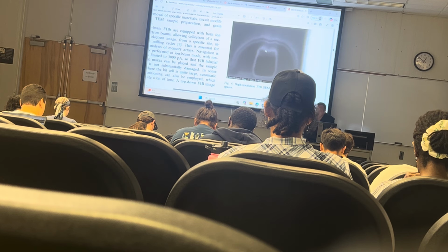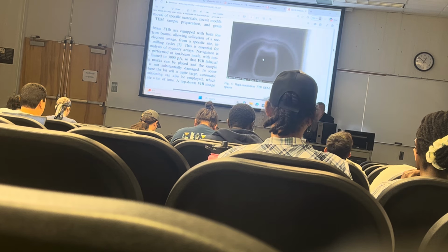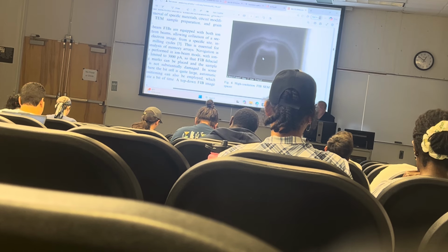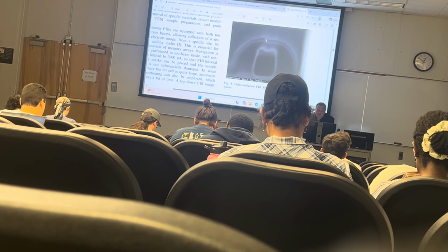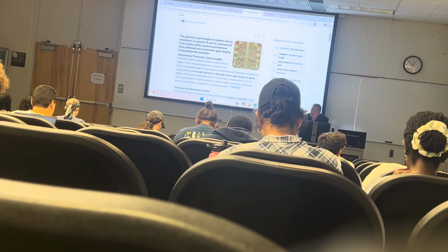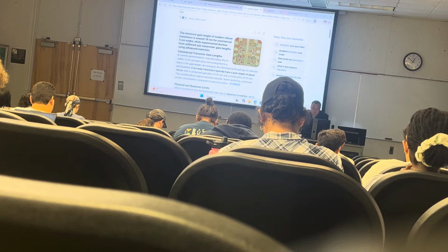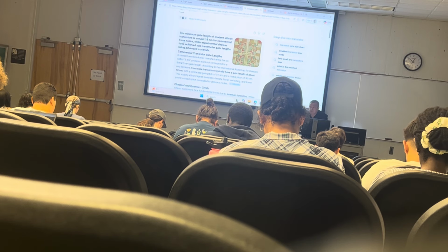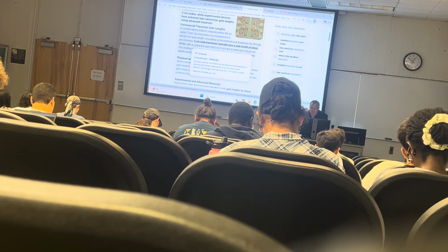Now, this is the transistor. So this is the gate, and this is the width of the gate. You can see this is about 90 nanometers. And the semiconductor nodes are measured in this distance. Because I don't know what the current node is, I just went in here, and you see here, the minimum gate length of modern semiconductor transistors is around 18 nanometers for commercial 5 nanometer nodes. So 18 nanometers. Contact gate pitch of 51 nanometers and metal pitch of 30 nanometers.